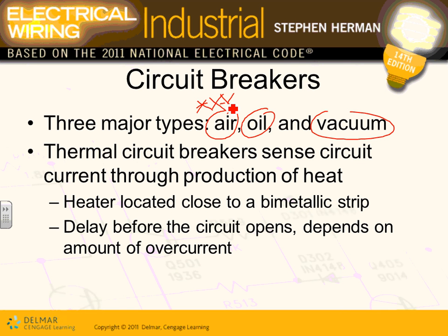Now what the heck is oil? The oil circuit breaker, guys, is where they immerse the contacts in oil. When they open, the oil extinguishes the arc. That's an oil circuit breaker. They use it in utilities, Adam, in high voltage. An oil circuit breaker is a tank full of oil. You're going to see in a second. They open everything in the oil.